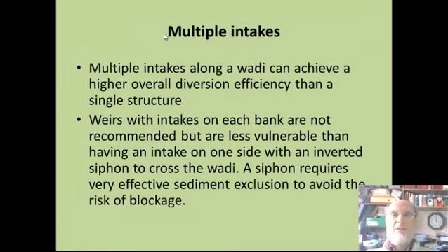So, multiple intakes can achieve a higher overall diversion efficiency than a single intake. They provide more opportunities to take water, and any flows used for flushing, or above the capacity of the upstream intakes, you can then capture further downstream.